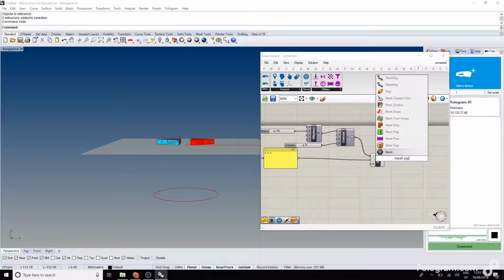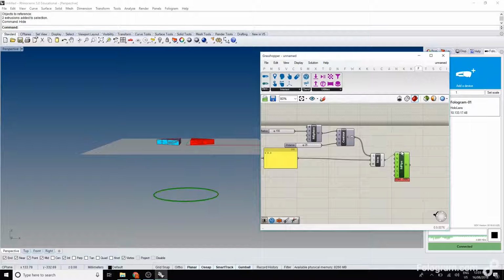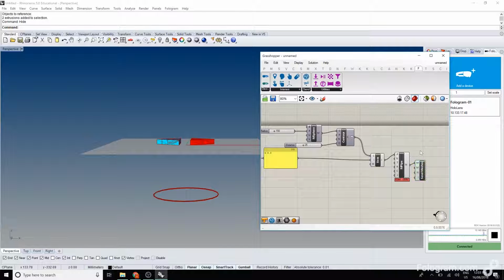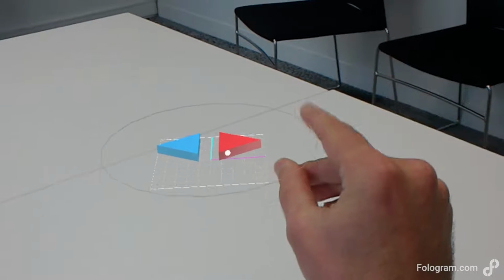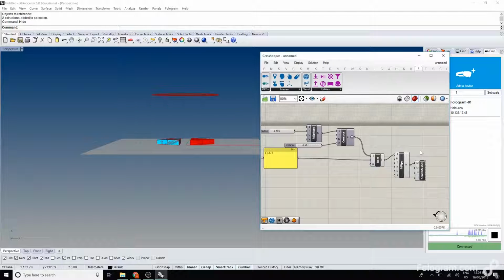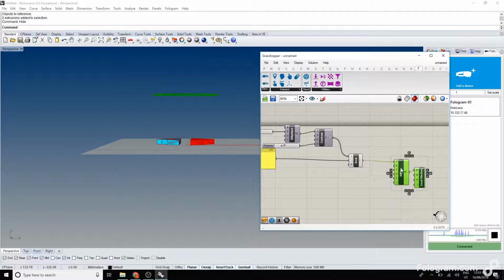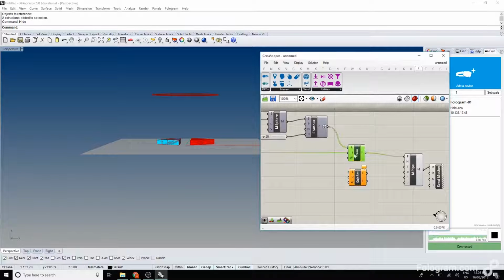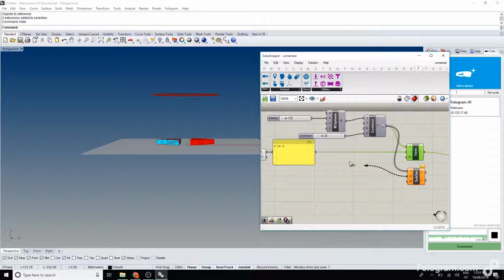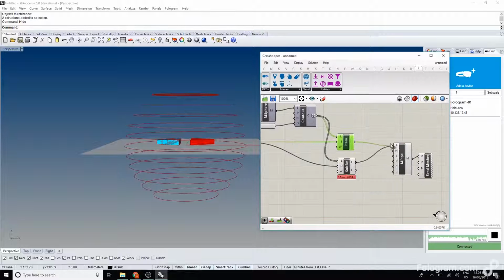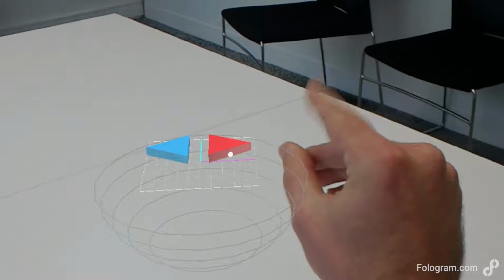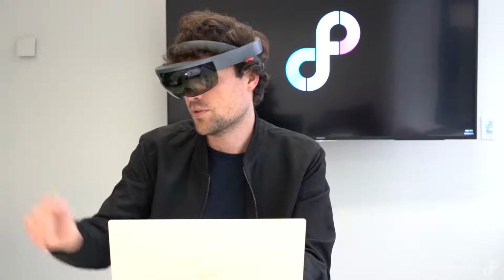Of course, we can mesh pipe this to send it over to the HoloLens, so we can actually see it on the headset. So now as I click my buttons, I can step through my contours. Beyond this, it's really simple Grasshopper stuff to change what you're displaying. We could use a sublist, for instance, which will show, rather than just a single item, it'll show everything up to the value that we're currently at. Okay, so then that's showing all of the previous contours as we step through.